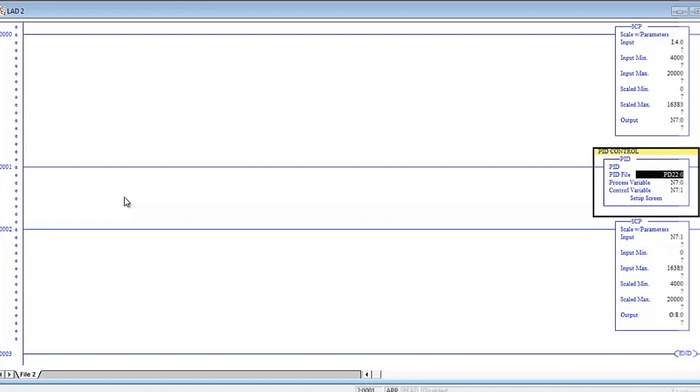Even the emulators that are made by Rockwell, the same company that makes this software, won't even execute a PID control. When you run the PLC program through an emulator, it just ignores that PID and won't start it, not in manual, not in auto.